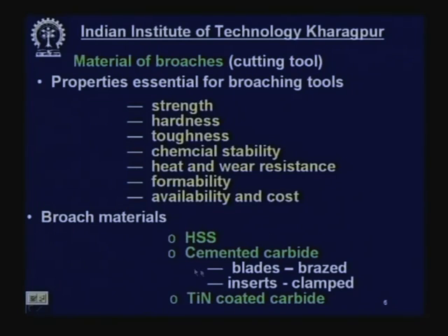Now, this cemented carbide, even high speed steel cutters can be coated. Carbide tools can be coated with titanium carbide, titanium carbonitride, titanium nitride and so on, but if it is high speed steel, best is titanium nitride coated tool, which will give longer life and better performance.